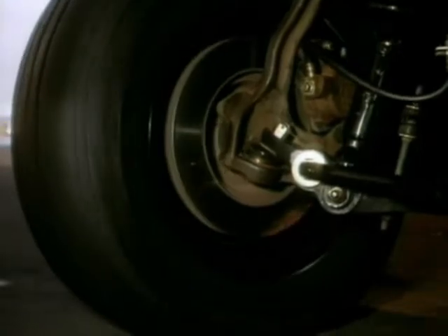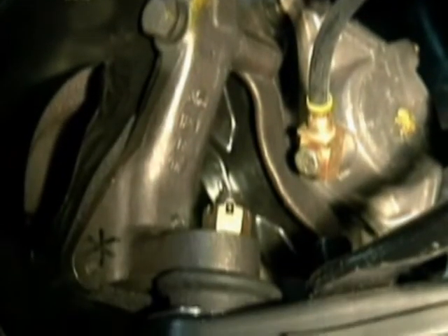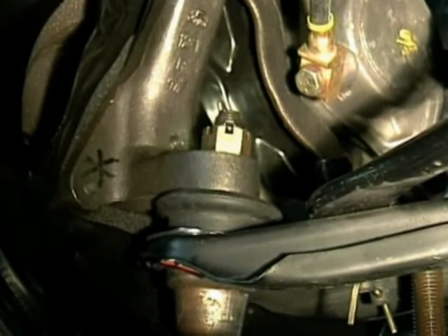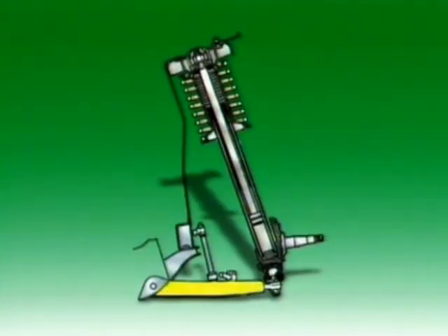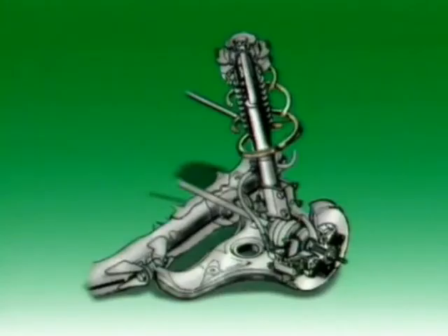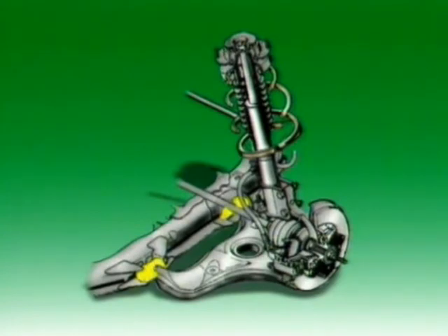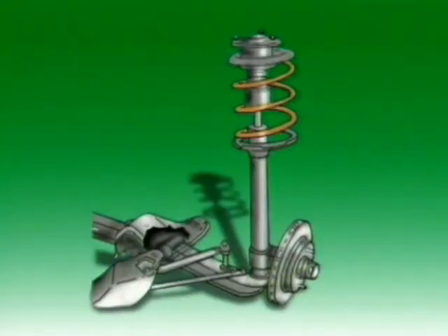The arms must be strong enough to withstand the forces due to normal operation, but light enough to minimize the vehicle's unsprung mass. The front suspension can have one or two control arms. Parallel link front suspensions have two control arms. Vehicles with strut-type front suspension have only one arm. It can be a wishbone shape with two fulcrum mounting points or straight with a single fulcrum.